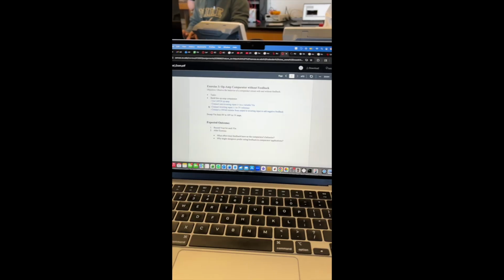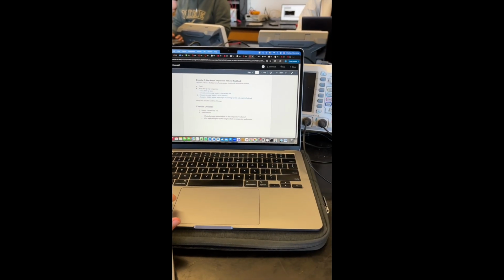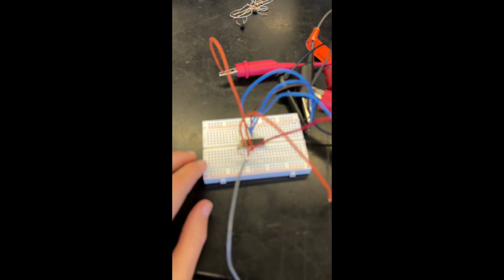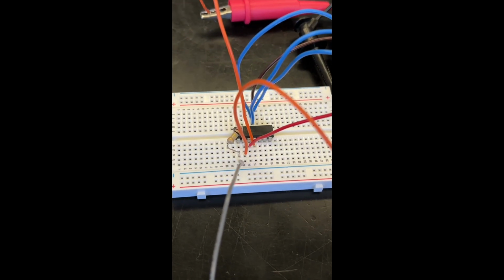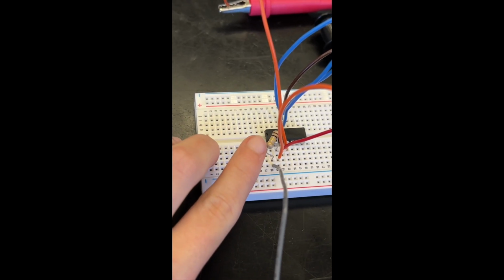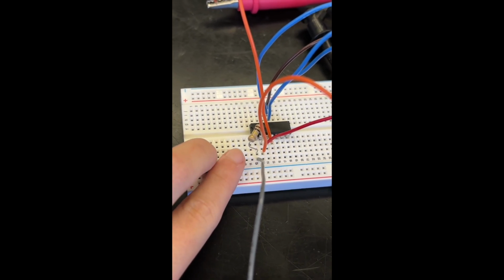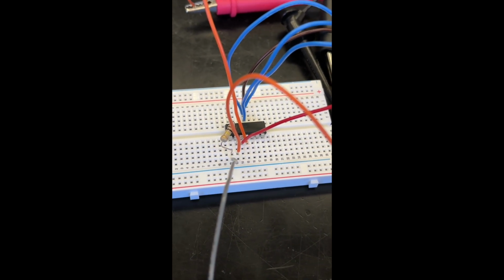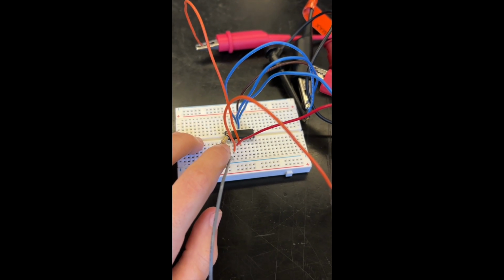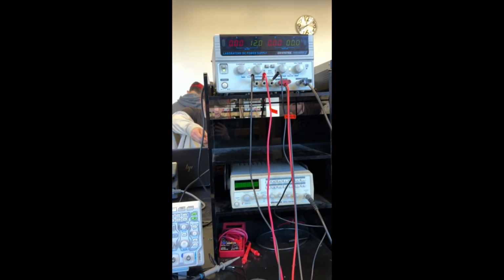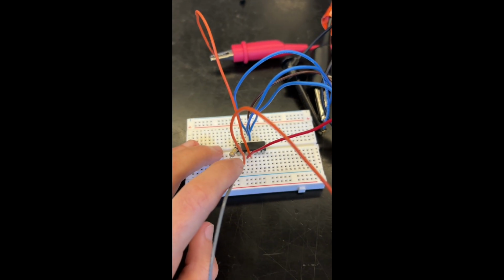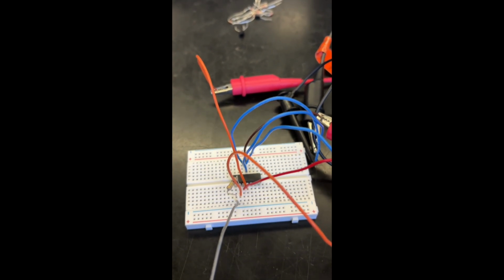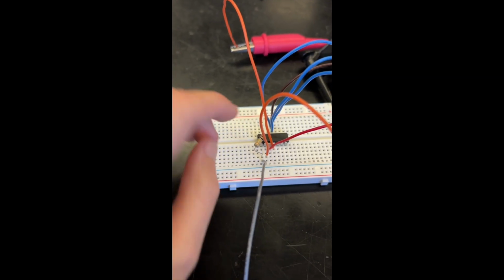All right, now I'm on exercise 3 of the final, where we have an op-amp comparator with feedback. So right here, I have my op-amp, and I'm using this 100 kilo ohm resistor as my feedback. So I'm just looping it from the output back to the inverting node. And then I'm supplying the VCC with a fixed 12 volts, and I'm supplying a 5 volt reference to the inverting node, so to the second node right here.